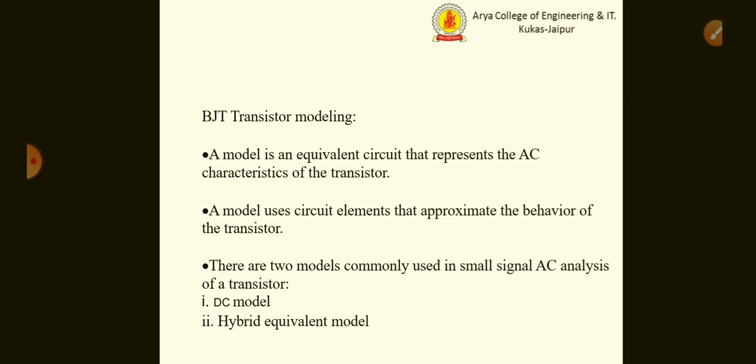The BJT transistor modeling. A model is an equivalent circuit that represents the AC characteristic of the transistor. A model uses circuit elements that approximate the behavior of the transistor. There are two models commonly used in small signal AC analysis of a transistor.